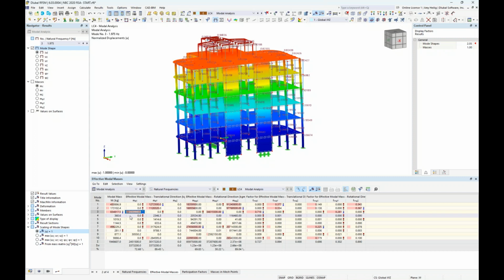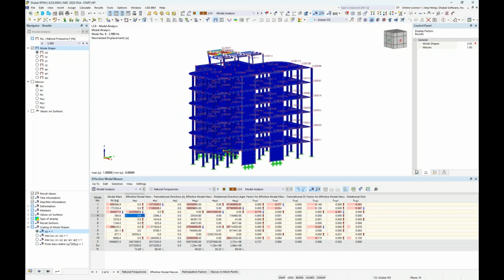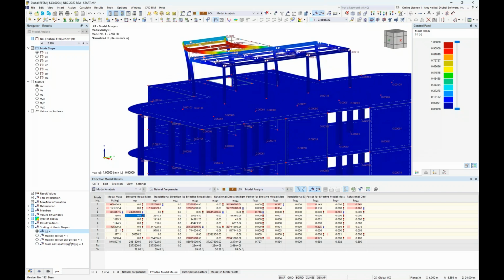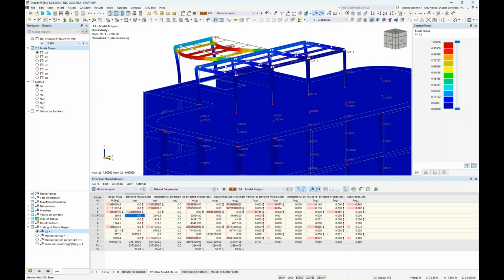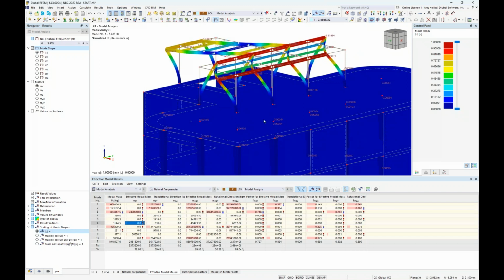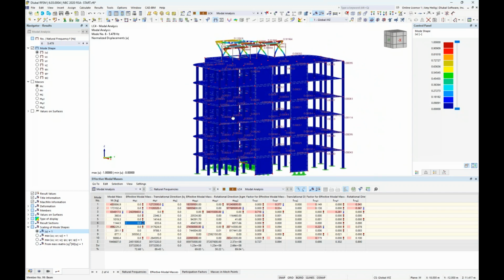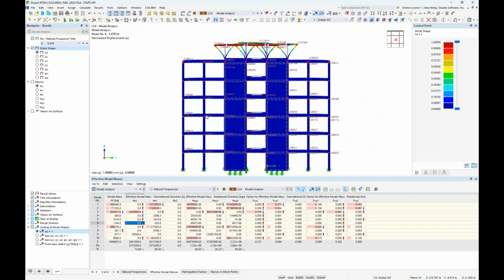Alternatively, if we take a look here at mode shape number 4, for example, you'll notice that really not much is going on with a majority of the structure. Rather, we're seeing a response up here for these smaller steel members only. Same concept with mode shape number 5 and mode shape number 6. So we term these usually as local modes, where again, not much mass participation, but we're seeing very little response for just maybe a few members. So I'd really like to eliminate these local modes in my calculation.